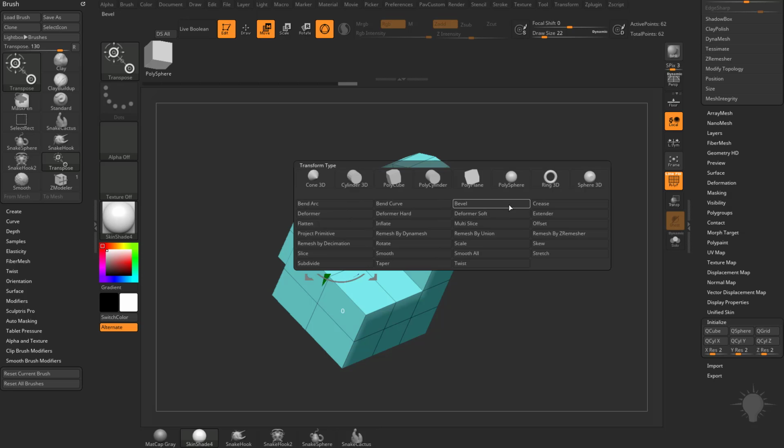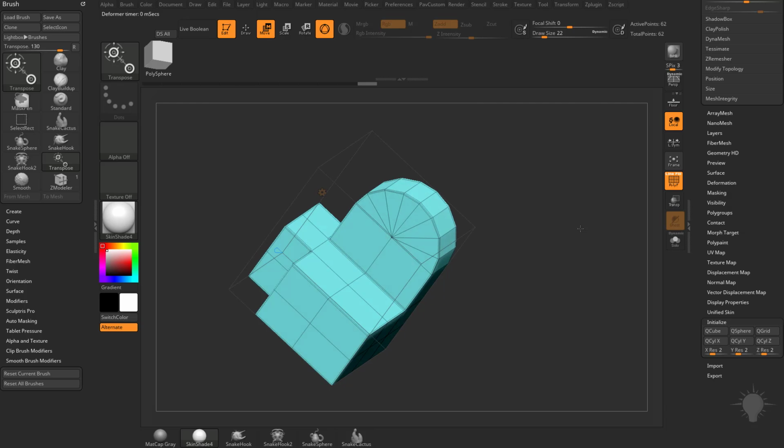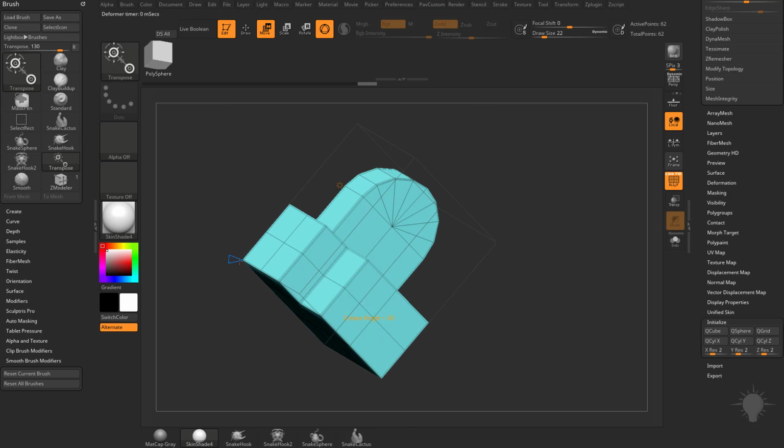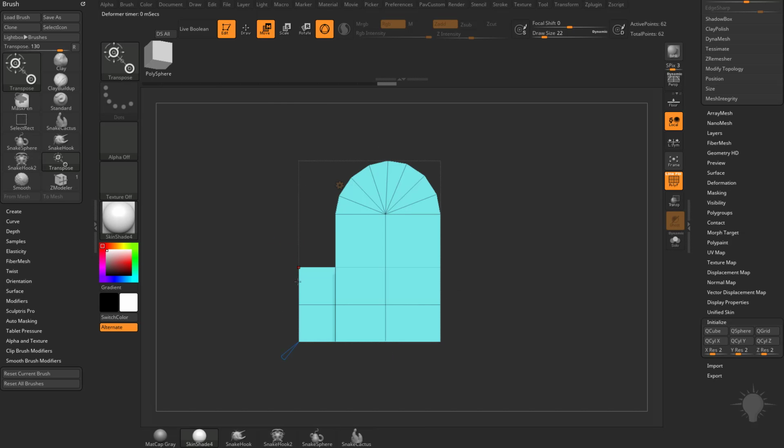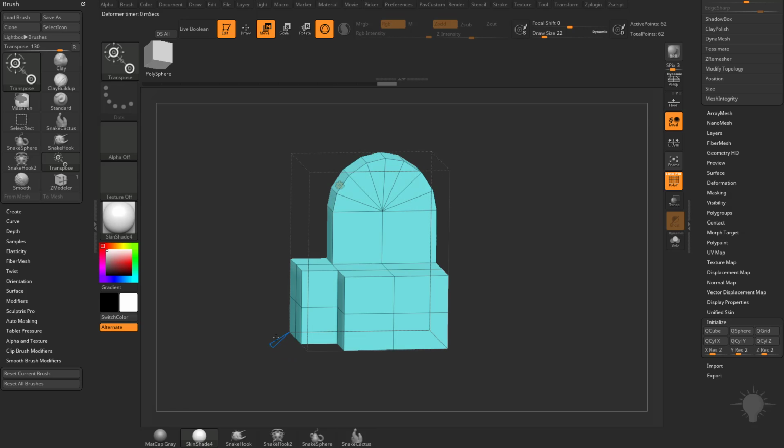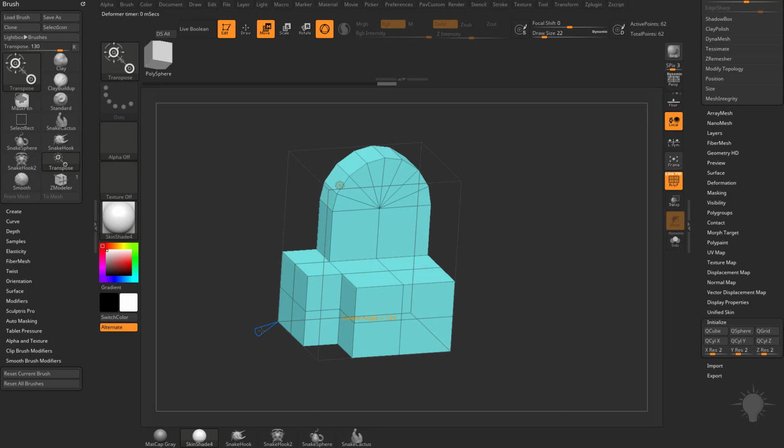And next to bevel, we just talked about, we're going to do crease. And crease works in very much the same way. You only have one slider here, and that's going to choose the crease angle. So as we drag this higher than 90 degrees, just like we talked about, if these angles right here are 90 degrees, if you're higher than 90, it's at 129 right now.